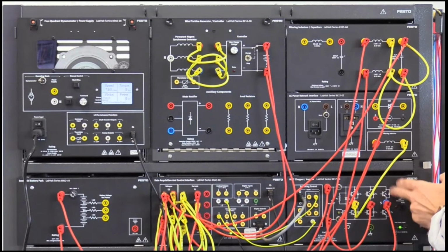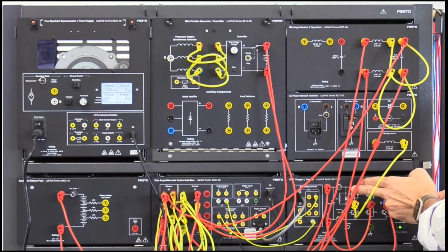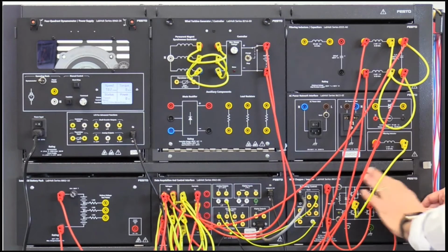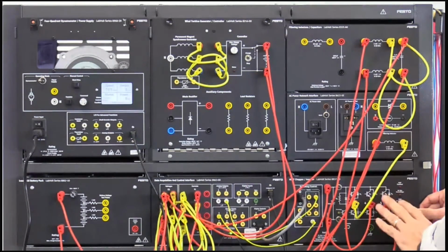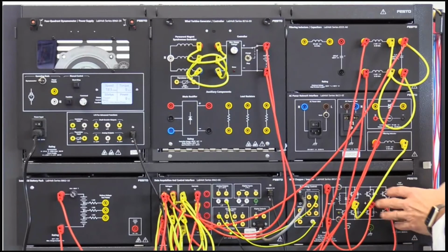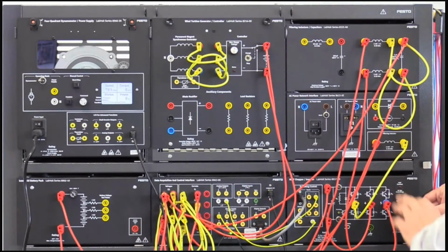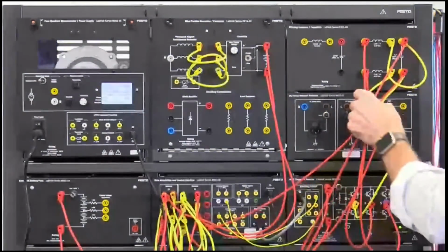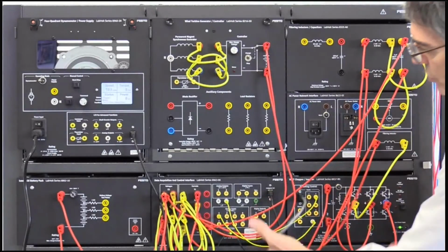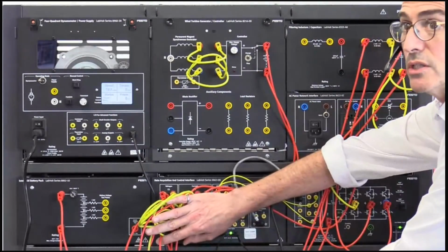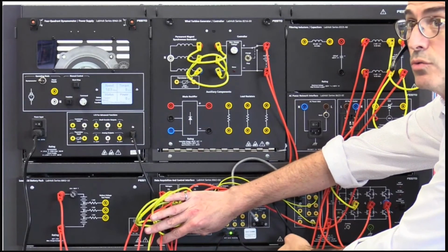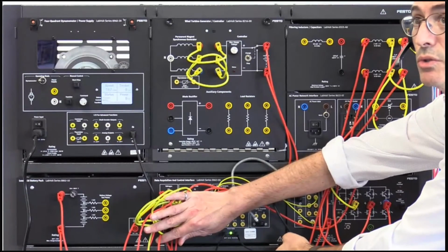I go to my transistor module here, which will implement the DC chopper and also the single phase inverter. We have 6 transistors in this module, so it can combine both functions in a single module. And out of that, we go to the filter here, and out of the filter, finally, we go to the resistive load at the bottom here. We have a module to implement a resistive load, which, sorry, we don't see it on the camera.